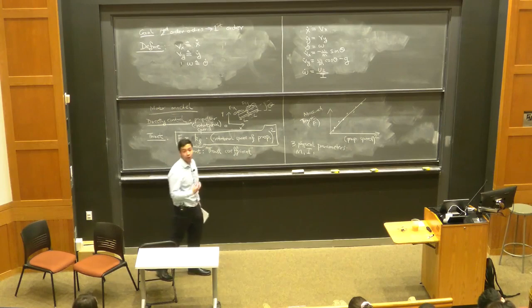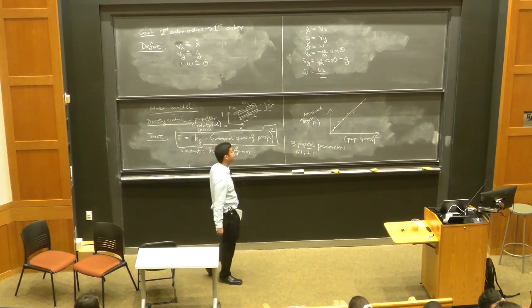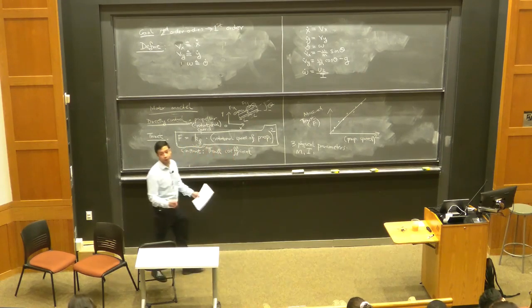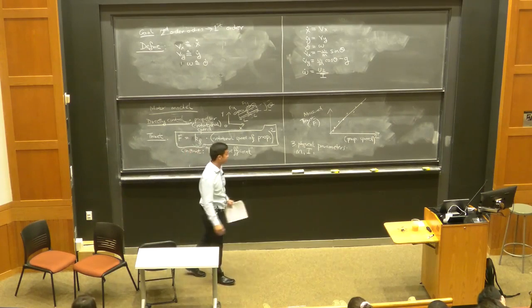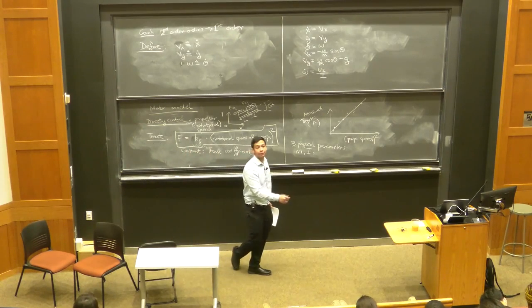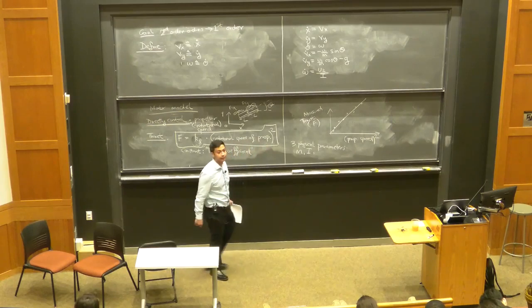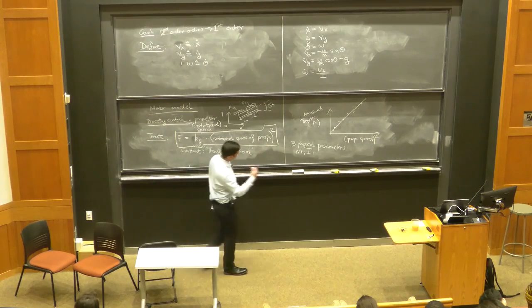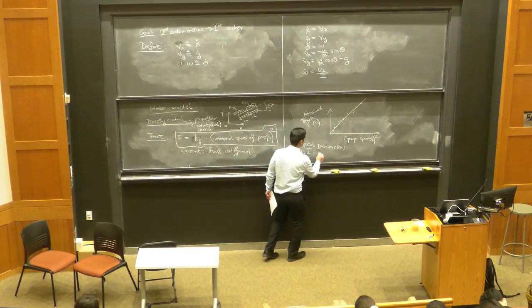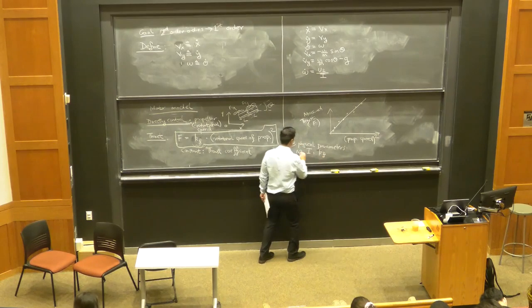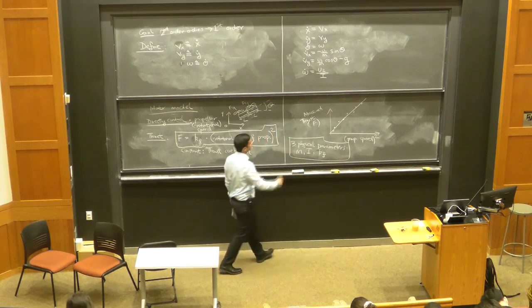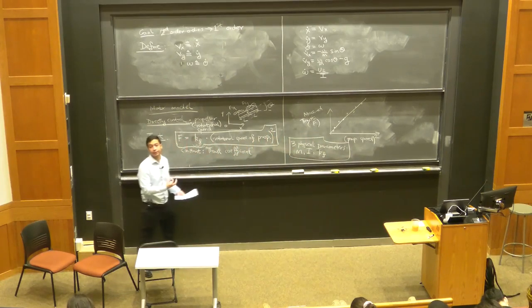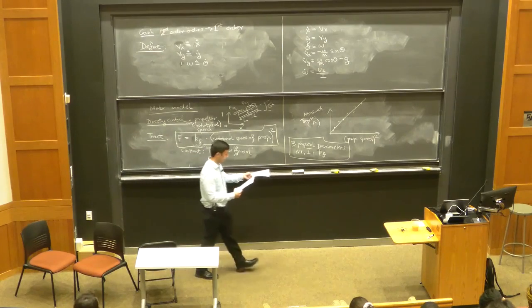Like I said, if you have a good CAD model, your CAD software is going to tell you what the moment of inertia is. There are also physical experiments that you can do. I can describe that maybe later if you're interested. That's actually what we did for the Crazyflies to get its moment of inertia, and then the thrust coefficient kf. If I give you these 3 physical parameters, that completely specifies the dynamics, at least for the planar quad rotor model. Okay.